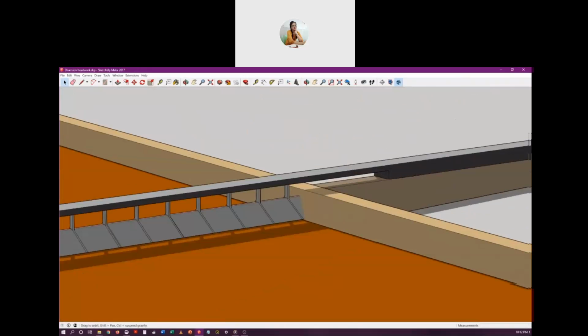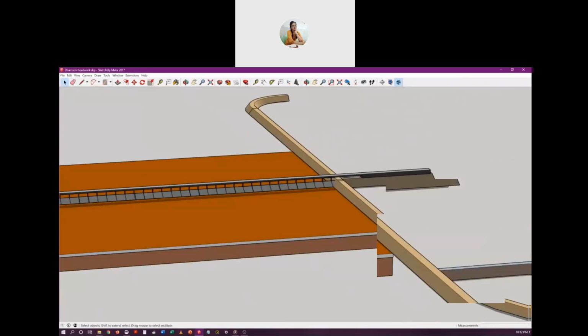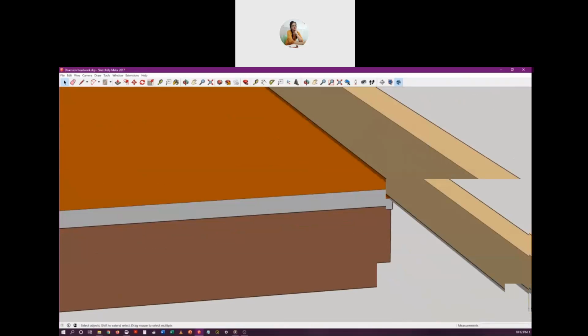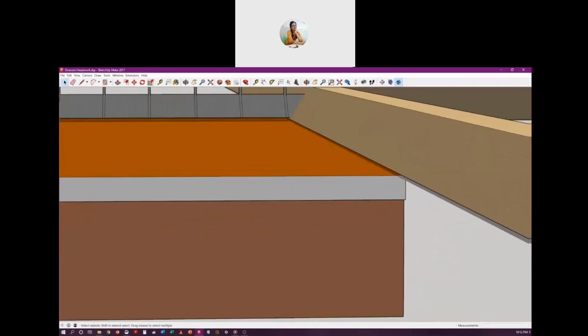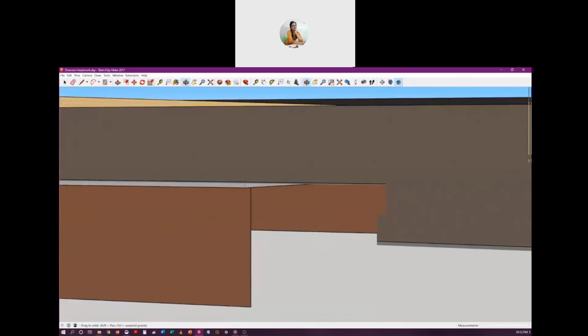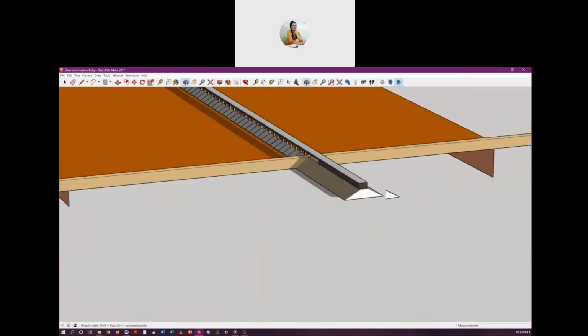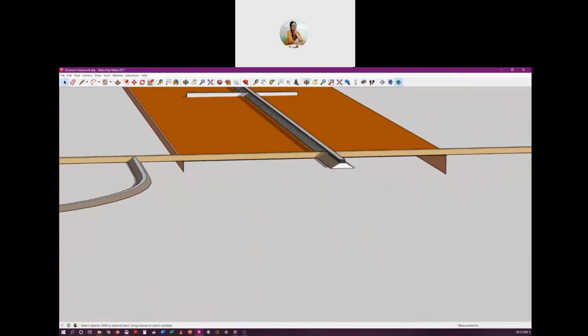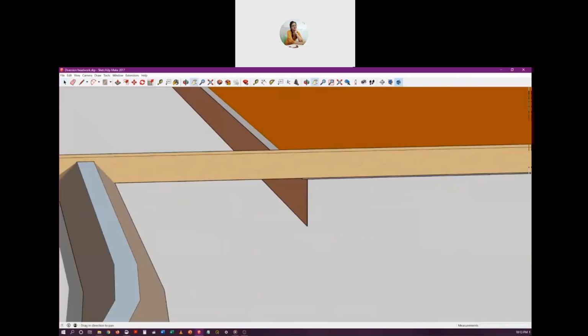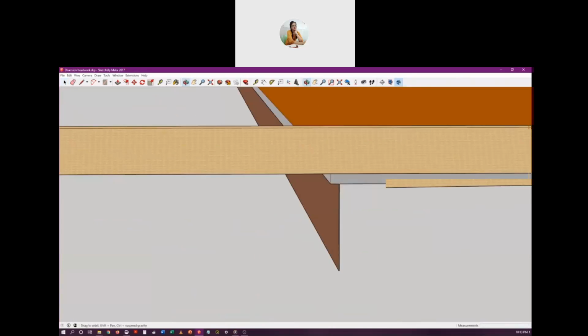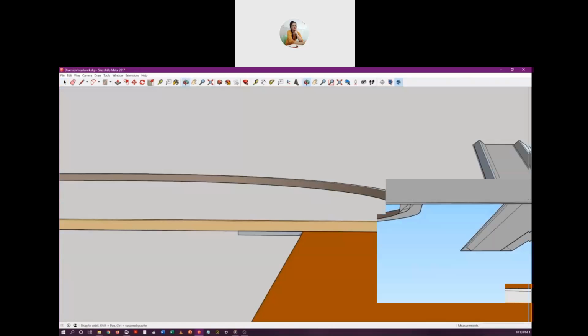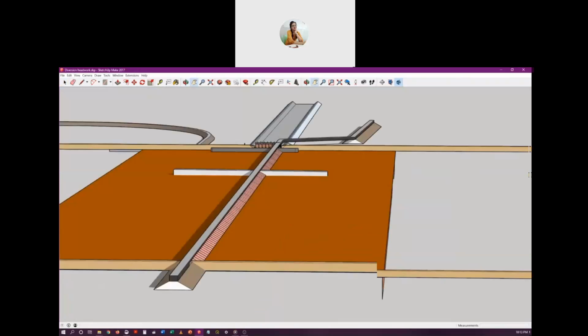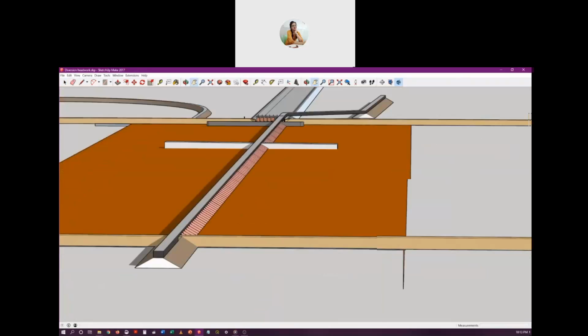And one more thing that I forgot to mention is that you see these cut-off walls or the sheet piles. These are provided here so that water doesn't simply flow straight from this point to the downstream end of the impervious floor. And because of provision of these kind of cutoffs, they'll have to take a longer path. They have to first go down, then up, then again horizontally, then again in this cutoff they'll have to go down, then up. So it increases the length of flow.